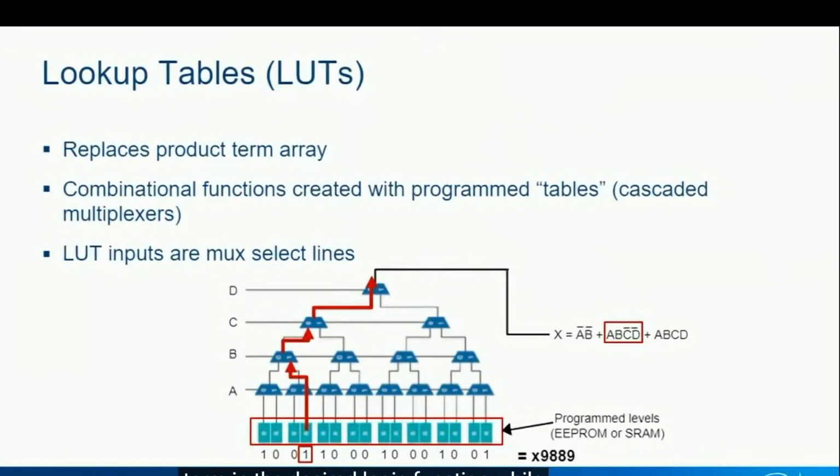While it may seem like more logic levels are required to produce outputs on a LUT versus CPLD macro cell, the flexibility of function creation and LE chaining, which we'll look at in a moment, provide improved performance and help to minimize wasted resources.